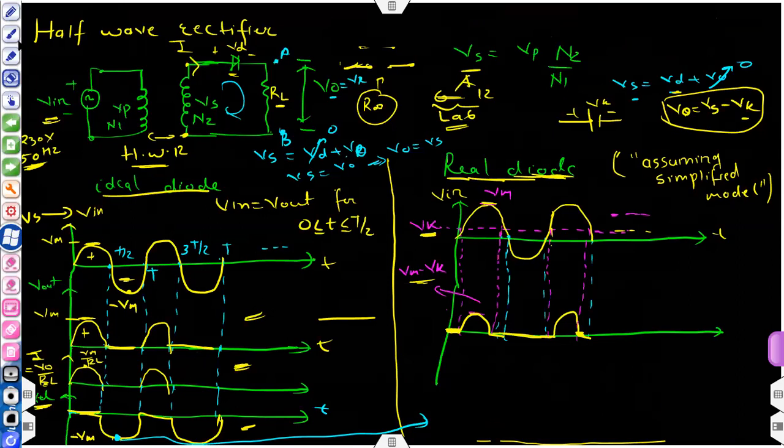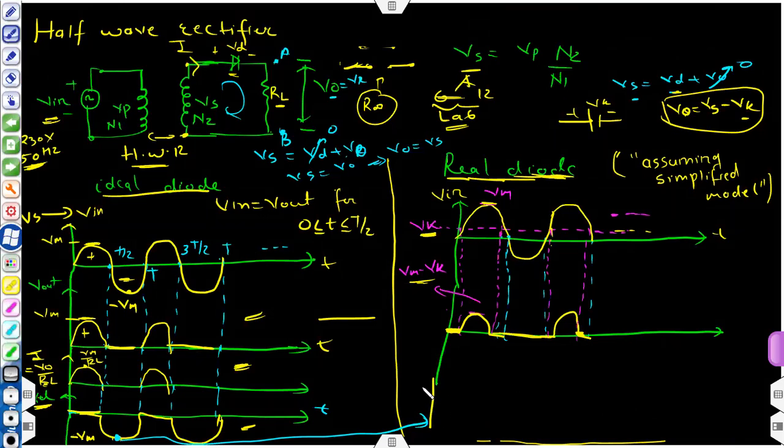So when your diode is off, I am talking about VD. Whenever your diode is off, it will simply follow the input voltage. In this, I am getting V out equal to 0. This means that this diode is dropping all the voltage across itself, so it should follow the input voltage, something like this. And after this, the diode is in on state, and it has a constant voltage drop across it, that is Vk. So a straight line.